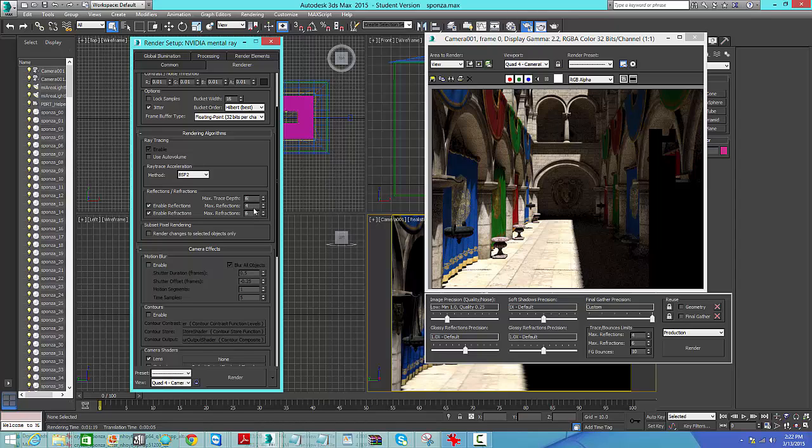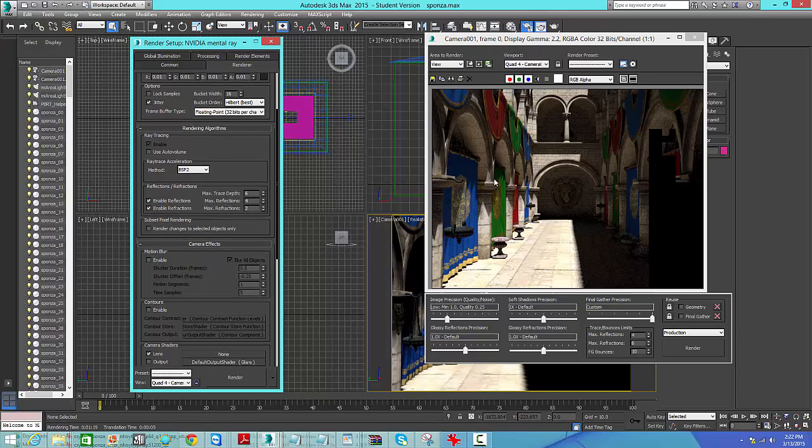So since this is over set, you're always going to hit the ceiling before this actually finishes processing the numbers that are here. So it's more beneficial to have this set to 2. And considering that there's nothing refractive in this scene at all, you could just turn refractions off and it wouldn't even matter. In a lot of these shots that you guys have, you don't really have anything that's a refractive material, so there's no reason to have refractions on, and it'll actually speed up your renders without changing the way the render looks.